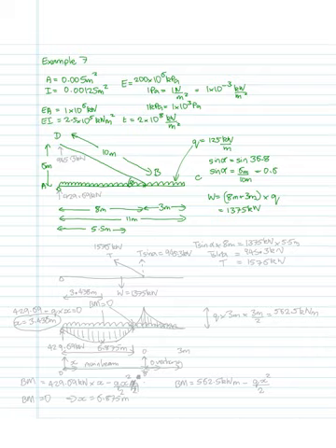Now, in terms of the force acting, let's take out the beam again. So we're just considering the beam, and then there's a tensile force T, which must be in tension, and it must be pulling in the direction that we've just shown. So two components to this, T sine alpha, and the horizontal component T cosine alpha.